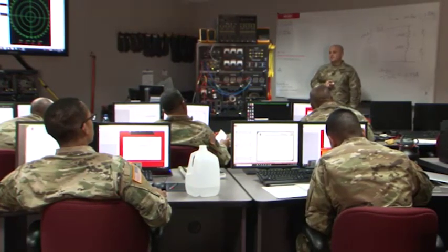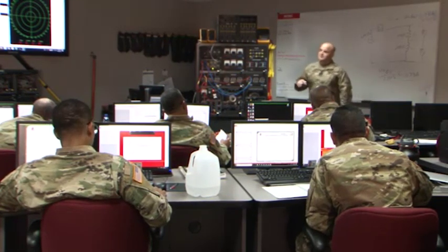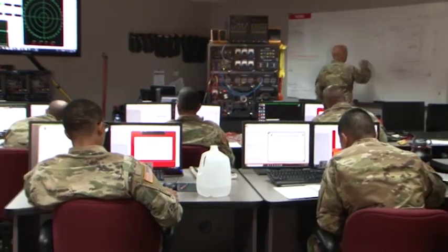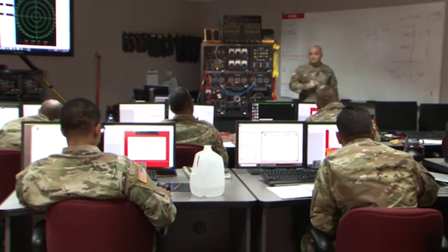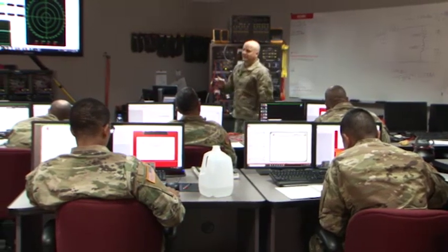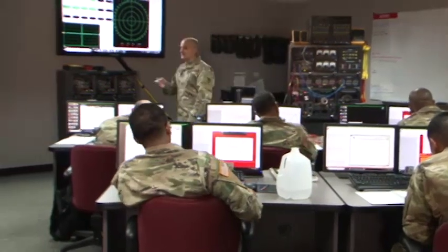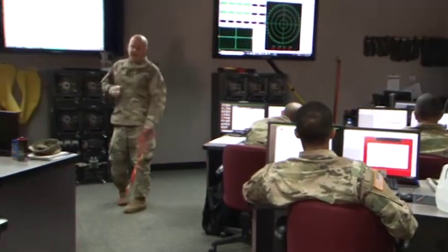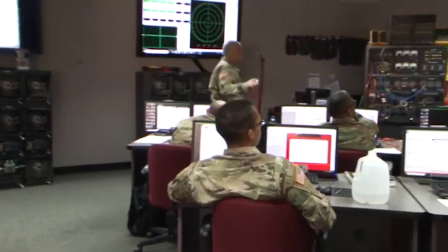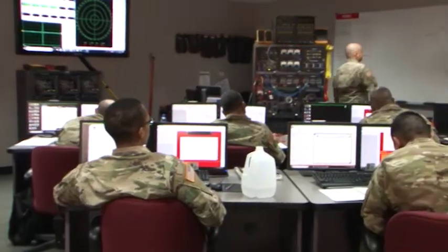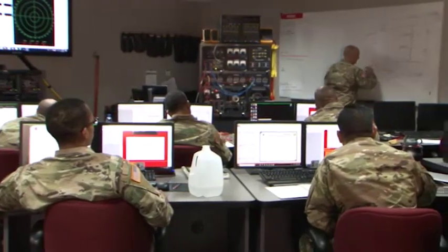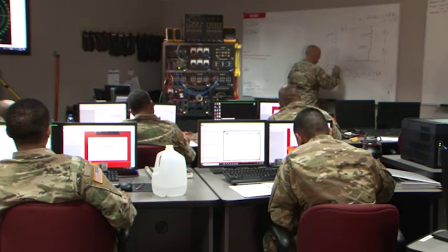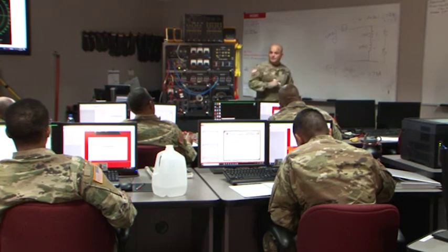I'm hearing all kinds of things. Okay. For series, it's a plus. In a series circuit, solving for impedance, which is represented by the Z, we're going to use Pythagorean's theorem, because that's a triangle, they're orthogonal, right? In an ideal inductive situation, they're perfectly 90 degrees out. So we can say that Z should equal the square root of R squared plus X sub L squared. Am I right there? We tracking?